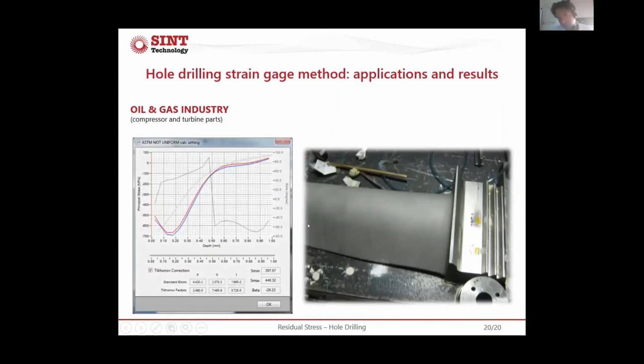And if you check the residual stress here, as we did, you see again in the left side, a typical behavior of residual stress with compressive state close to the surface, with principal stresses that are very close to each other, with some hundred of megapascal, but in this case, compressive residual stress. That is good if we think that then this component will be subjected to an additional tensile stress in operation. So this was just to give another example and to complete also the presentation.